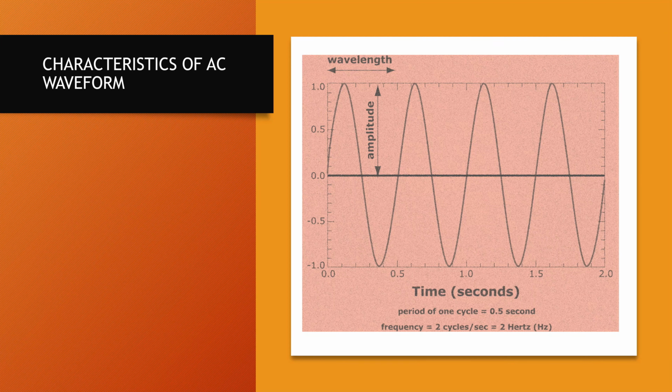It is necessary to understand some of the terminologies because now we have digital or microprocessor relays which can be hooked up to a computer, and you can see the voltage waveforms and the current waveforms, and using that you can identify what caused the fault and where the fault was caused. But in order to understand that, it's necessary to have our basic concepts clear.